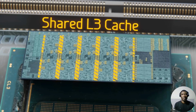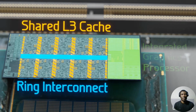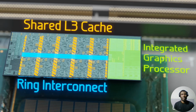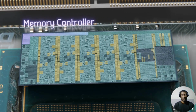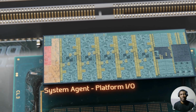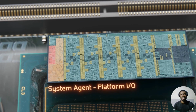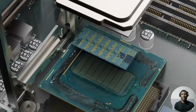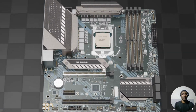Let's now zoom out and look at other sections of the CPU. To the side of each core is the shared L3 memory cache and ring interconnect. On the far right is an integrated graphics processor which functions as a less powerful GPU. In the top left is the memory controller which sends data to and from the DRAM. And finally, on the far left is the system agent and platform I/O, which communicates with the chipset on the motherboard and manages the flow of data between many of the other components in your PC. So with that in mind, let's move on and look at the motherboard.